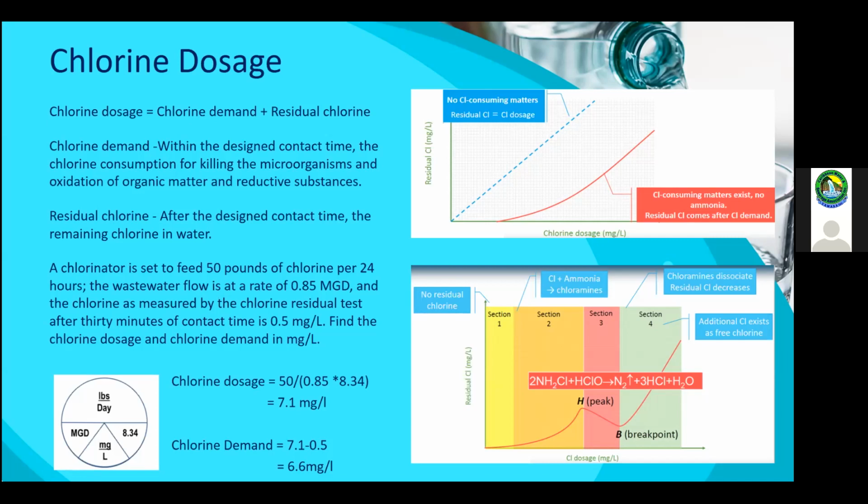Your breakpoint chlorination is a point where the chlorine level exceeds the oxidant demand and the water begins to build a residual of free available chlorine. Theoretically, exceeding your breakpoint prevents increased levels of disinfectant byproducts like your chloramines.